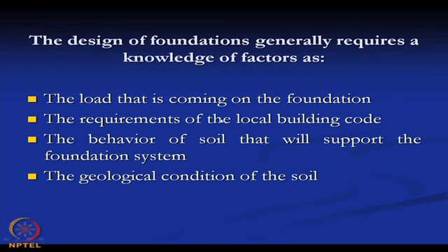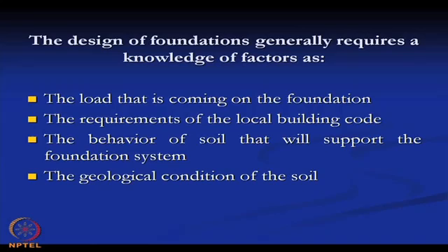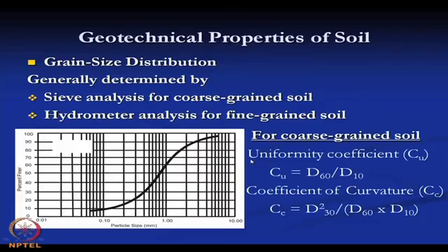Then what are the required design codes, the building codes of the area where we are designing the foundation, and the behavior of soil that will support the foundation system, what will be the soil properties. We should know the soil properties before we start the foundation design, what their behavior is. To know those soil properties, we have to go for soil exploration, laboratory as well as field testing. And then the geological condition of the soil is also required.